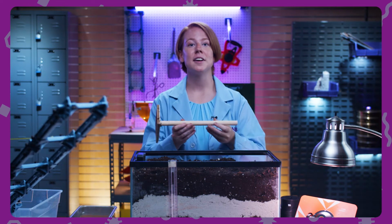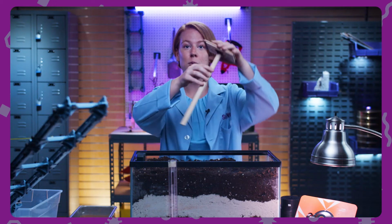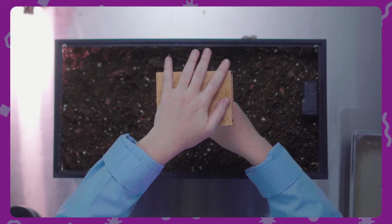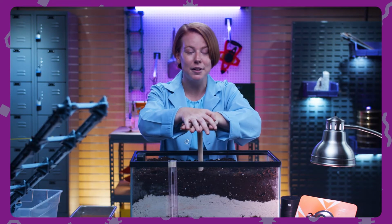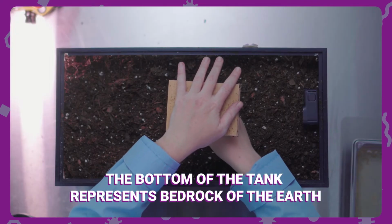Next, let's test a deep foundation, represented by the dowel. And specifically, this is an example of a piling foundation. So we're going to hold on to the block side of the wood and point the dowel towards the soil and slowly start to push it down. As we drive the dowel into the ground, it becomes more difficult as we reach a greater depth. If we push hard enough, the dowel actually reaches the bottom of the tank, and this represents bedrock in the earth. This will give the foundation more stability.